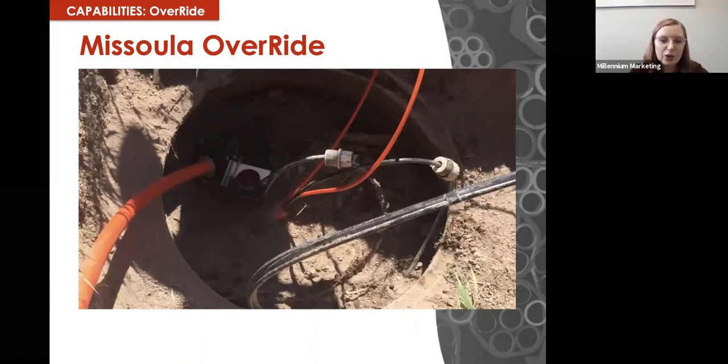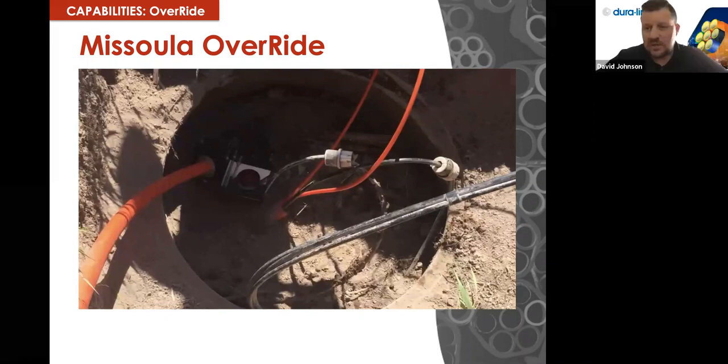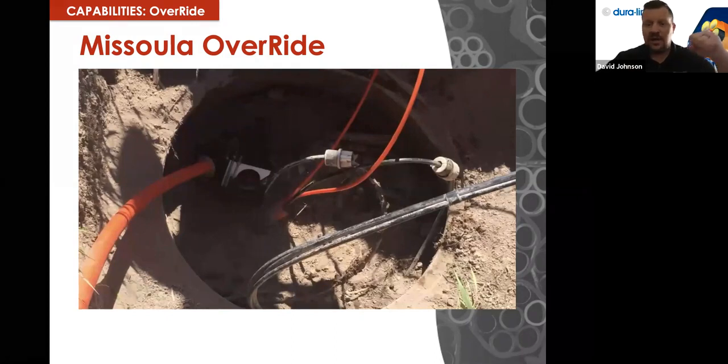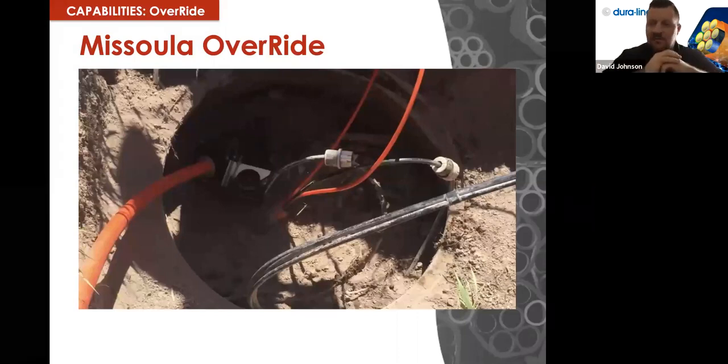But we do have another question of how do you pressurize the microducts on the reel? That's a great question. So these are the things that Frank said that they sell, right? It's a matter of hooking up your air compressor. It's a valve. It's kind of a handmade situation where we've got our couplers that then go onto a pipe that goes into our created valve, where it's a turn off and turn on valve.